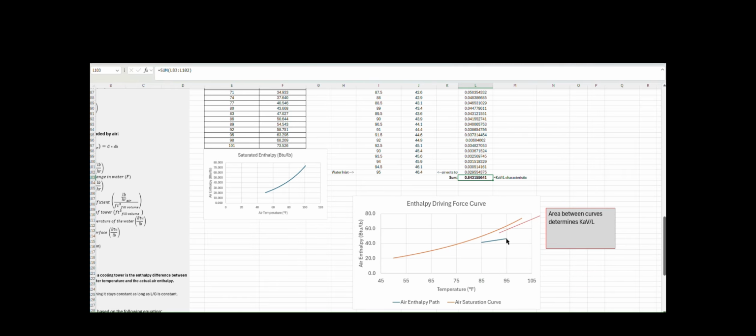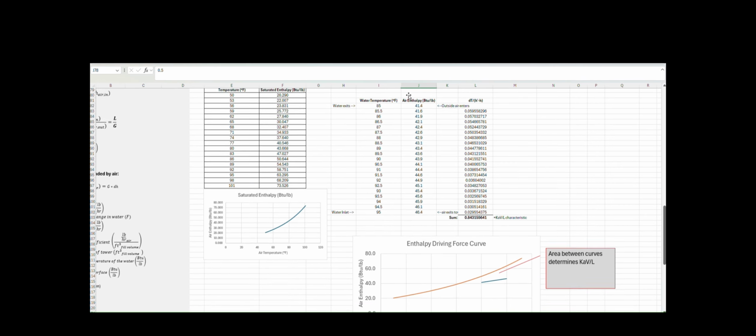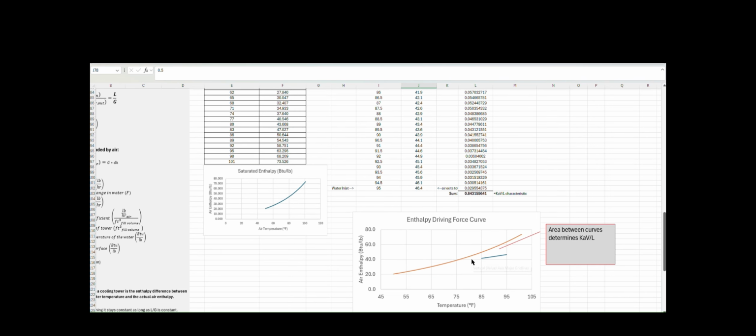That means that your temperatures, let's say you've got a 10-degree delta, this is going to shift to the left. That means that you're going to be supplying colder water out of your tower, and you're going to get colder return water from your process. And intuitively, that makes sense because what we said is to get this number lower, you're going to increase your flow rate of air through the tower. So if we increase our flow rate of air, we get colder water.